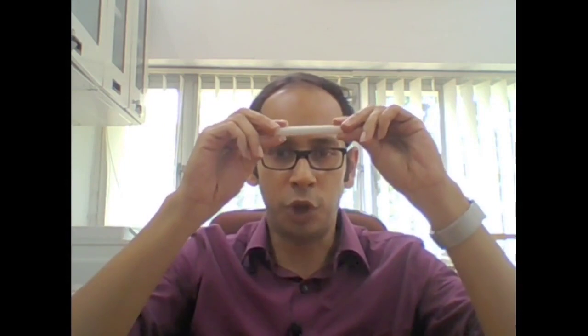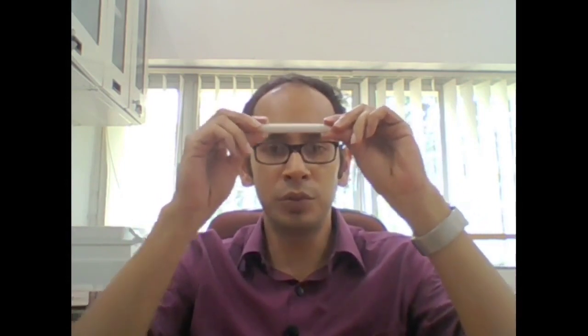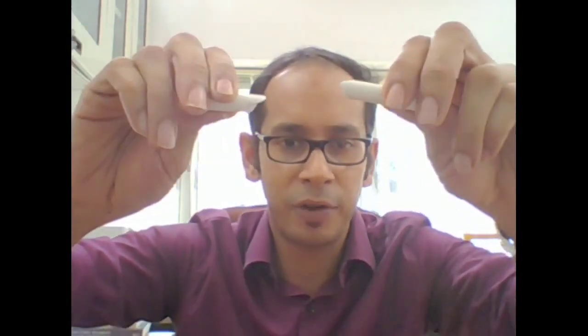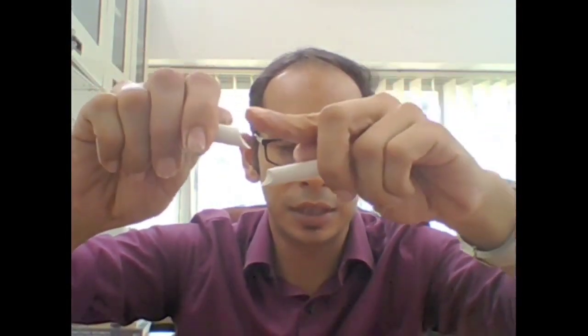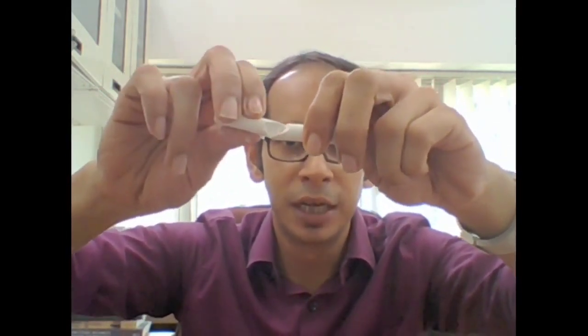So this is a classroom chalk. To this chalk, I am applying a torsion at both the ends. I am not pulling or pushing, I am simply applying a torsion, and this is a brittle material which is weak in tension as well as compression. Mostly in tension; in compression it may be better. If I just apply this, and you see at what angle it failed, it failed at that 45-degree angle. Over here you see this kind of an angle which it has made, and similarly you can see over here. So this one fails at an angle of 45 degrees.